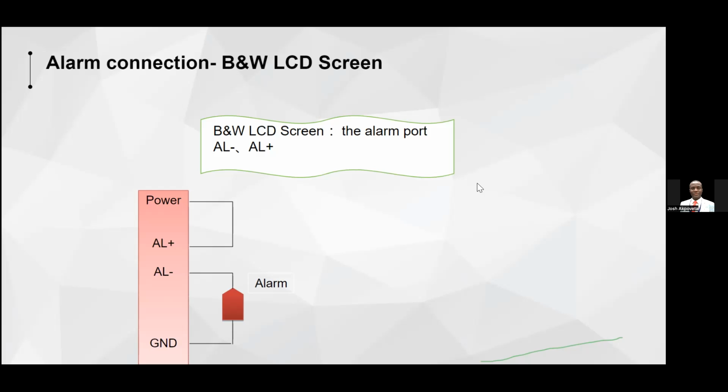There is a break glass. There is an accessory that is called a break glass. Most times when you go to a facility, you see a glass, mostly in red, with the inscription, in case of fire, break this glass. When you break that glass and you push that button, what it simply does is trigger a command that allows the relay to open. Your door opens automatically in the event of fire.